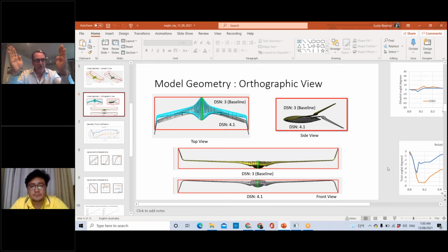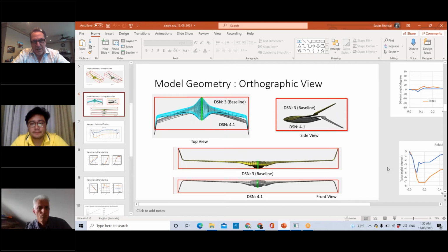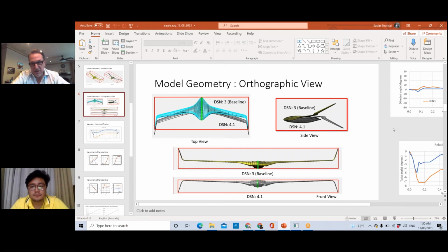I could unsweep it to load it up, or I could add more toe in to load it up, and they might have similar vortex drag benefits. It would just be interesting to see if that's the case. But what you say does not totally surprise me. And I think when we all look at this as a practical matter, it would clearly be really hard to keep that stiff enough for what we all want to do. So we probably need to unsweep in any case, some amount.